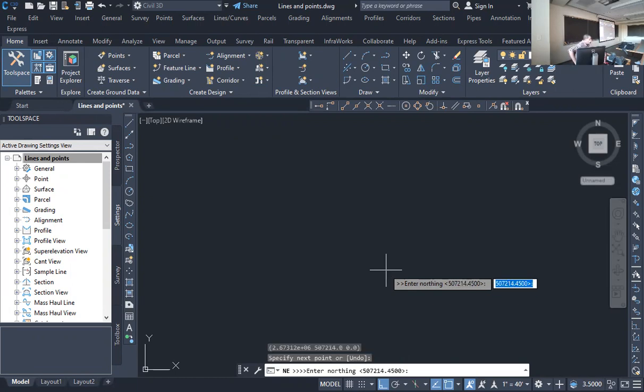Please check me and make sure when you do your own that I didn't transpose a number. Do I make mistakes? You are damn skippy, I do. Right? All right, so northern 507,194.31. So now I'm entering the coordinates of the spire at Colton Chapel. 2,672,995.5.